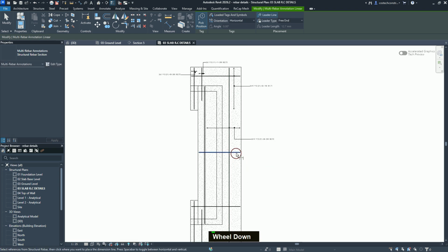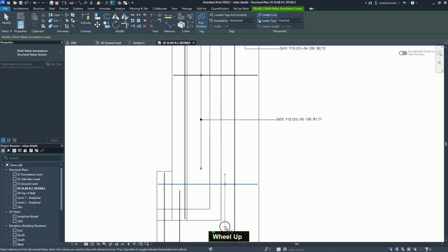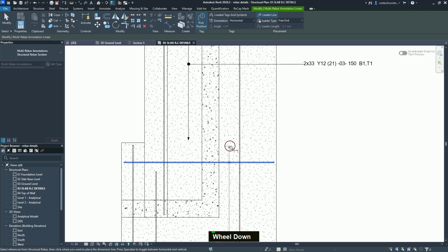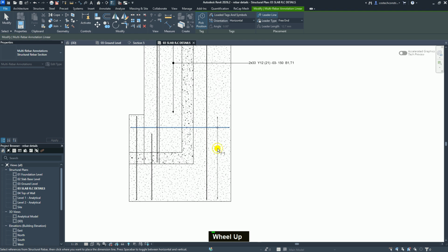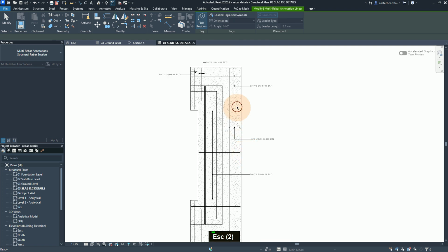I will pick this other Rebar set. With its line, I'll give it somewhere here, or we can detail the line here. Then we can come again, and now we can snap it to the endpoint of this side here. We can proceed to pick the next Rebar set, and you see that we see where the set is spanning using the annotation we have just created. So we can place it here. I'll pick this point and we can snap it here. I will hit escape a few times.